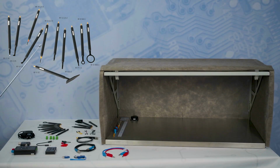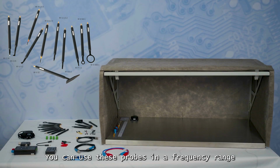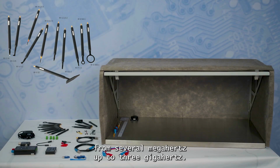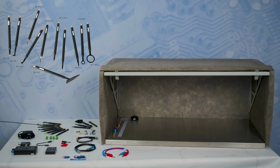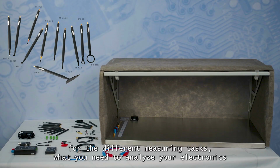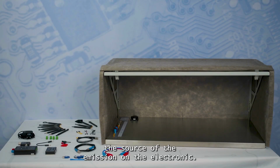And the last ones, what you can see here, are a lot of near field probes, different types of near field probes. We have electric field probes, we have magnetic field probes. You can use these probes in a frequency range from several megahertz up to 3 gigahertz. And you see here that we have different sizes of the probes and different probe tips for the different measuring tasks, what you need to analyze your electronic and for the troubleshooting and to find the source of the emission on the electronic.